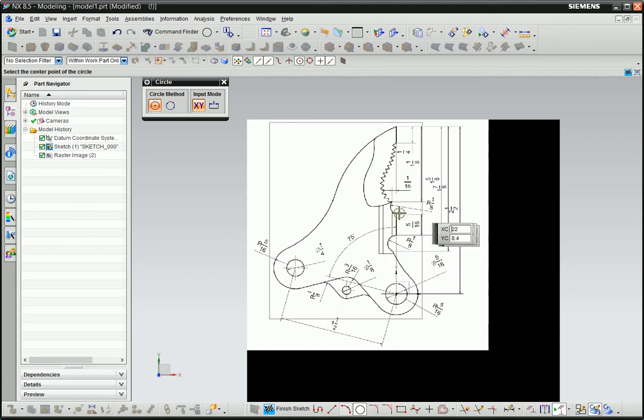That's the wire cutter part. So we should draw this big piece first, and you want to start with the holes, as that's your critical dimension. It's very critical for assembly. So we should start from these two holes, and it's going to be this dimension and that dimension.